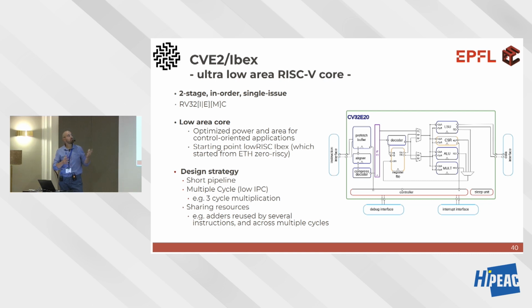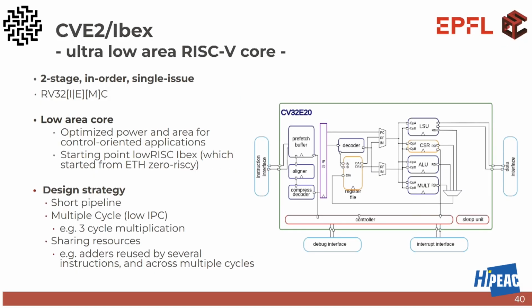Going back to technical, what we are going to do today is looking a bit at the pipeline. Of course, I'm not going to read the Verilog line by line and explain how the CPU is designed, but the idea is that in case you are using it or extending it or modifying it, or you are just curious about the design strategies, you can understand more or less how things have been designed. So as you see from the graph here, the CPU goes from left to right.